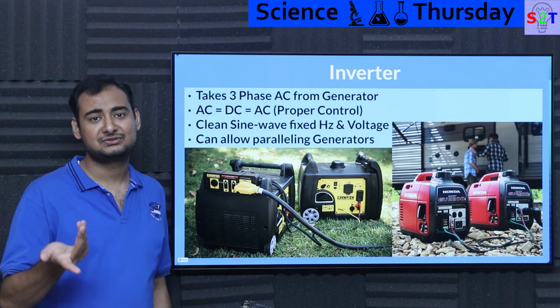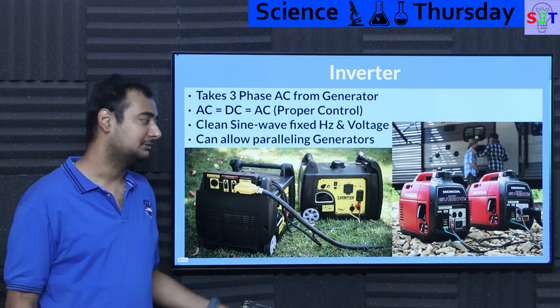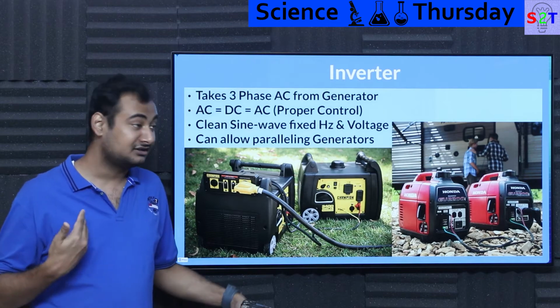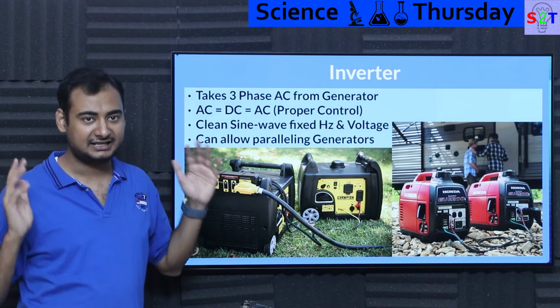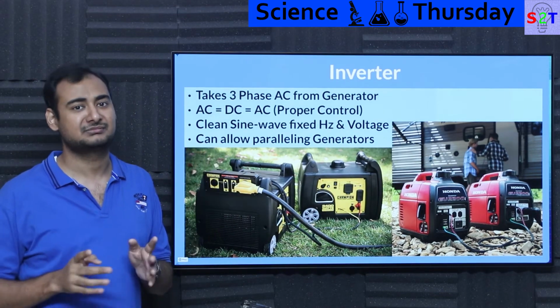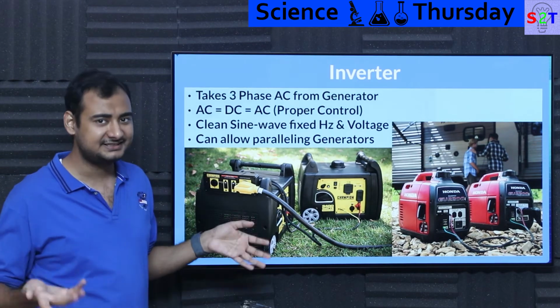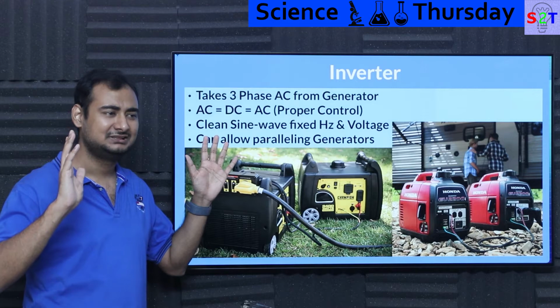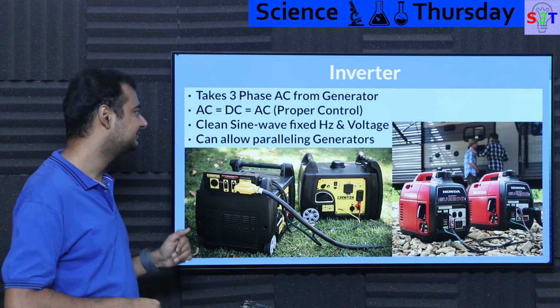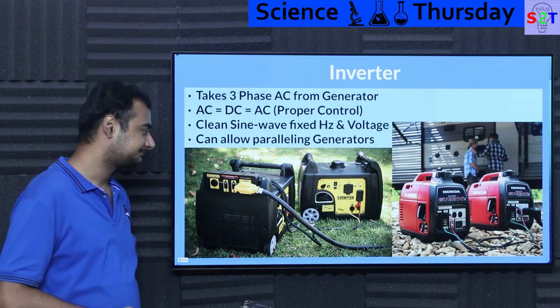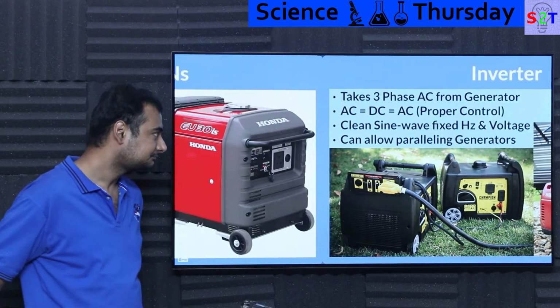parallel these things up? Well, assume you bought one of them and then your load went up. Rather than buying one bigger one, you can just buy another smaller one. And sometimes from a redundancy point of view, that's better. The likelihood of both of your generators failing at the same time is very low. So people do like this sort of paralleling operation. It's not that feasible or practical, but it's one of those things where it's better to have it than not to have it. So people do like the idea, and you get really good electricity coming out of these puppies.